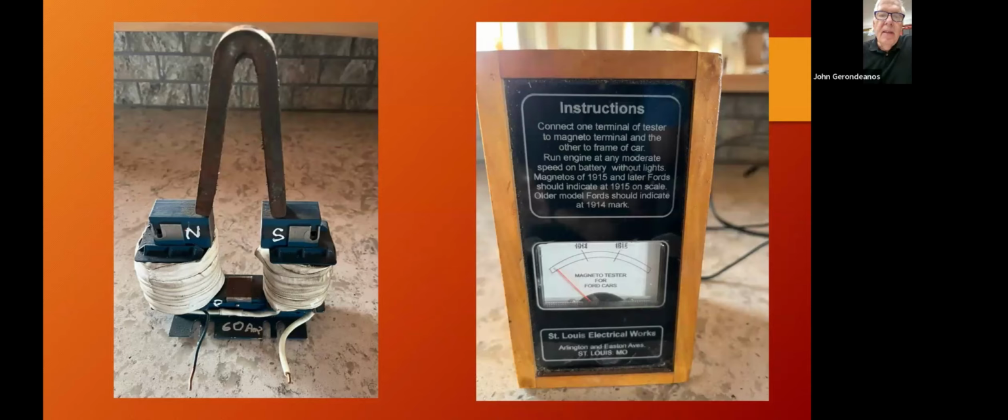And on that magnetizer, he shows the magnets for size. And this is a really well-designed piece of kit. And if you can see on the diagram or on the magnetizer, he's shown that he uses 60 amps with it. And it's a thick piece of wire on, I guess, a 2 kVA transformer that's been modified. And that's a very suitable steel. The laminations magnetize very quickly, and the field collapses very quickly. It'll help you magnetize your magnets really quite well.